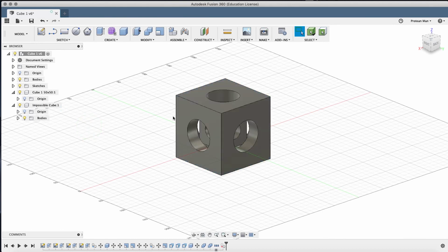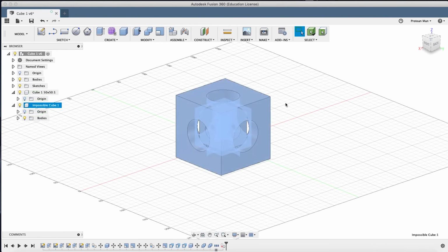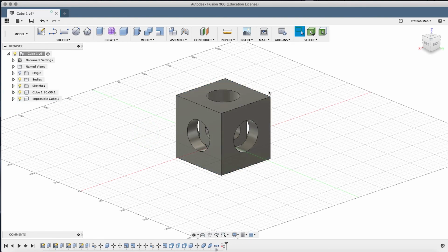This is important that we do this because if I want to do some kind of interaction, let's say an assembly, which is up here, where maybe this has a hinge attached to it, well, I can now move that hinge and the proper bodies attached to that hinge will move, but the other parts won't, even though it's still inside a multiple bodied component. So this makes another layer of complexity if you want to actually do something. So that's it. That is the big lesson for today. But we're going to do some more after this.